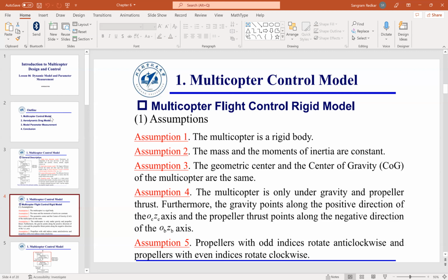If the aircraft is in level flight, you agree with me, the gravity is acting down. But if the aircraft is pitching up, the gravity vector, or the weight, is still going down. This is going to give you two components. One is going down and one is towards the x-axis of the aircraft. So the gravity vector is always aligned with the down in the north-east-down, Earth center, Earth fixed coordinate frame.